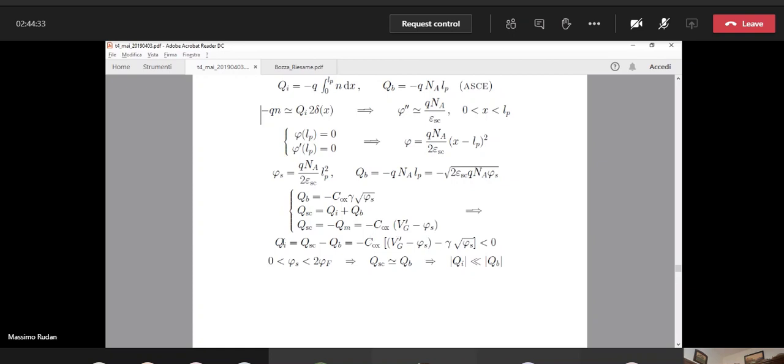So this expression is able to provide a relation connecting the surface potential here with the inversion charge when we exclude accumulation, okay? It is not able to give us independently Qi and phi s because we have been introducing approximations, okay? So this is not possible anymore.